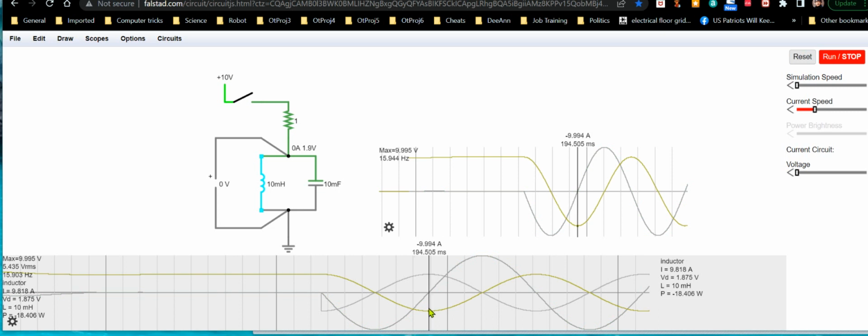Now it's time for the inductor to go back into a discharge cycle for the next quarter cycle. And it does, and as a result, right now it's generating a higher voltage across the capacitor than it has internally. So the capacitor is charging again now, but its current falls off as it charges.